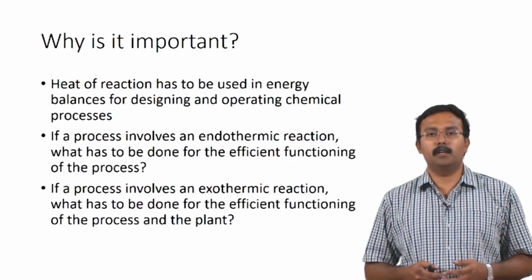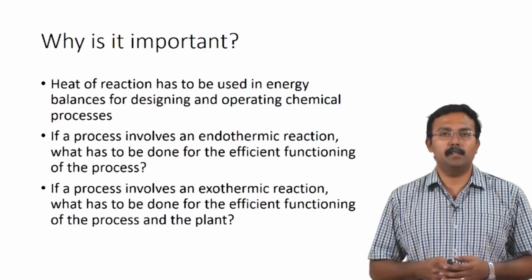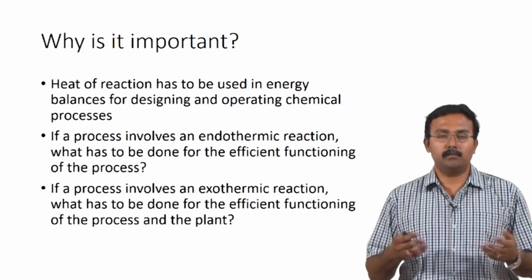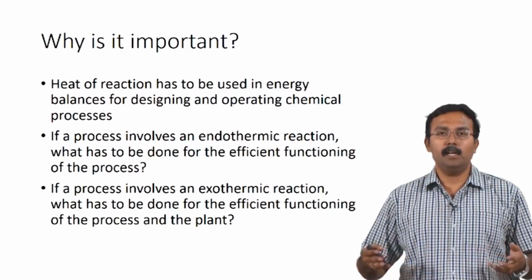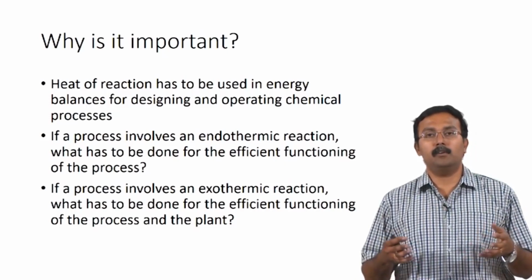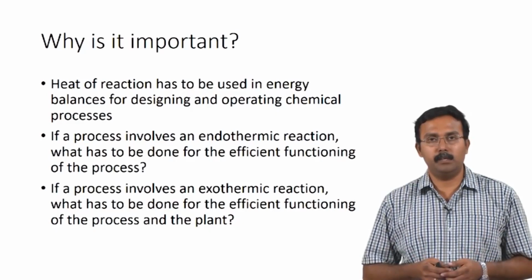Why is this important? Why do we want to maintain the temperature within desirable levels? For an exothermic reaction, if you do not cool it down, the temperature will keep increasing to a point where it can be a safety hazard or it can cause severe damage to the reactor and other equipment which is being used.